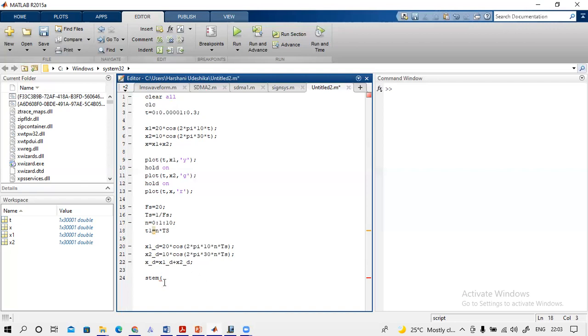So we have to plot our signal with respect to the t1 time value, not with n. If you choose n, it will take n as the time value, so you will have 1, 2, 3, 4 at time 1, time 2, time 3, likewise. But that is not a correct answer. This n refers to the number of samples, so it should be mapped to t time.